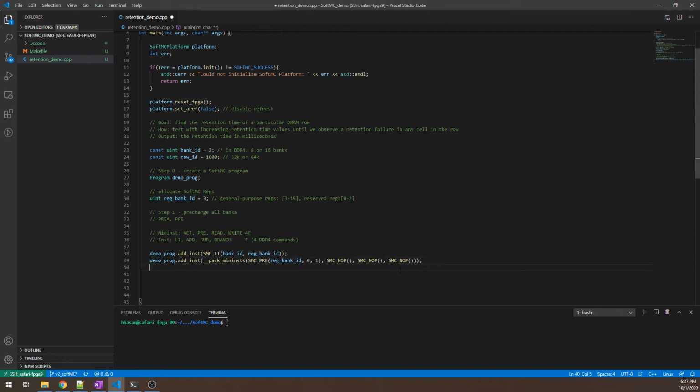So recall from the slides that DRAM commands are associated with different timing parameters. In order to complete precharge correctly, we will need to wait for the precharge latency. So here, let's define it as TRP. This is also how it's defined in the DRAM datasheet. So precharge latency, for short, will be TRP. Let's define it in cycles.